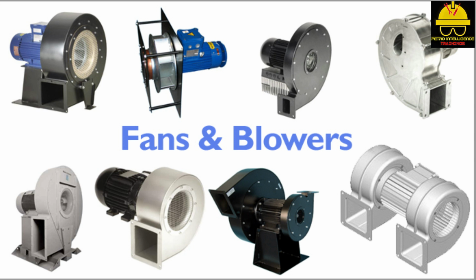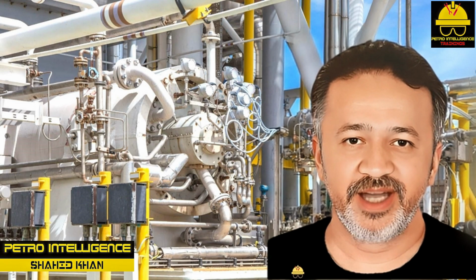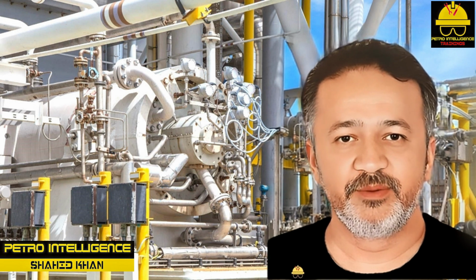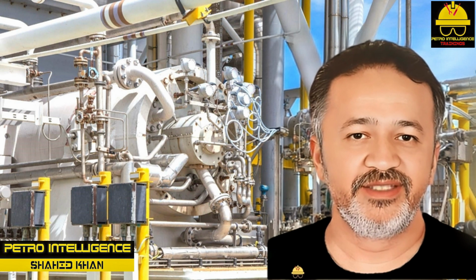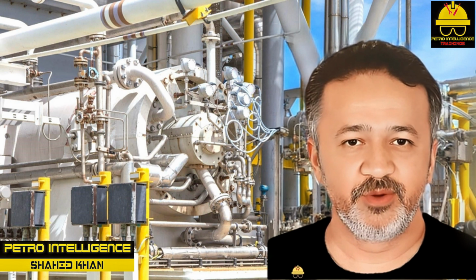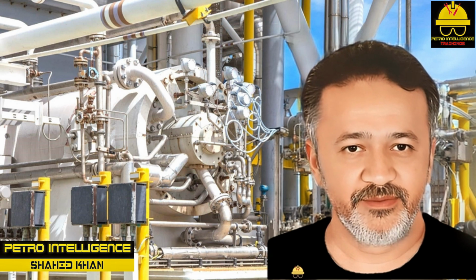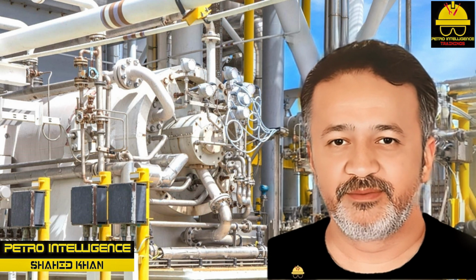Tube axial fans are mounted directly in the piped cylinder and are designed to move air or gas at medium pressures. The vane axial fan resembles the tube axial fan. The motor and fan are mounted directly in the tube. A series of vanes help direct flow over a wide range of volumes and pressures. Each of these 4 fans can be direct drive or belt driven.